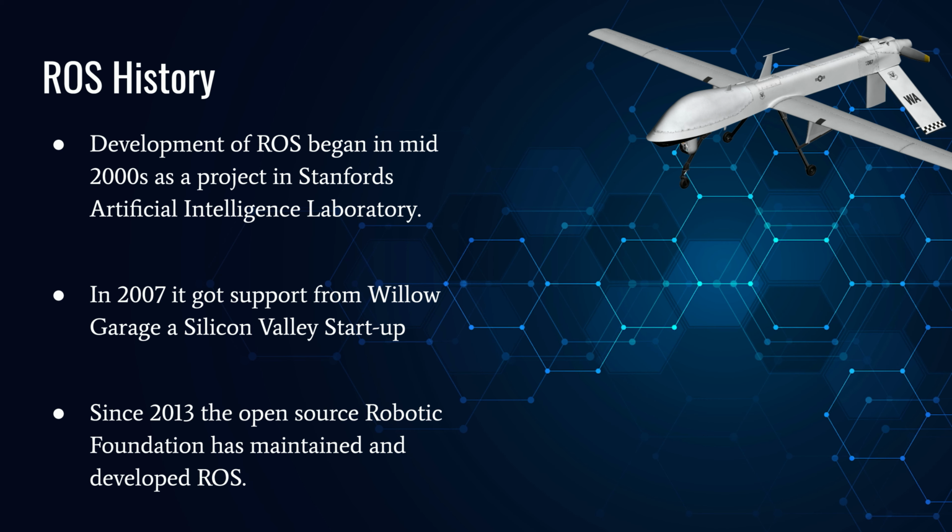it should be distributed, meaning that a program can be run on multiple computers and communicate over a network, so it's not developed specifically for one device and contained within that. And it is also multi-language supported, meaning that you can essentially write modules for ROS in a lot of different programming languages, for example C++, Python, MATLAB, or Java. Basically, whatever language has client library support for it can be used.